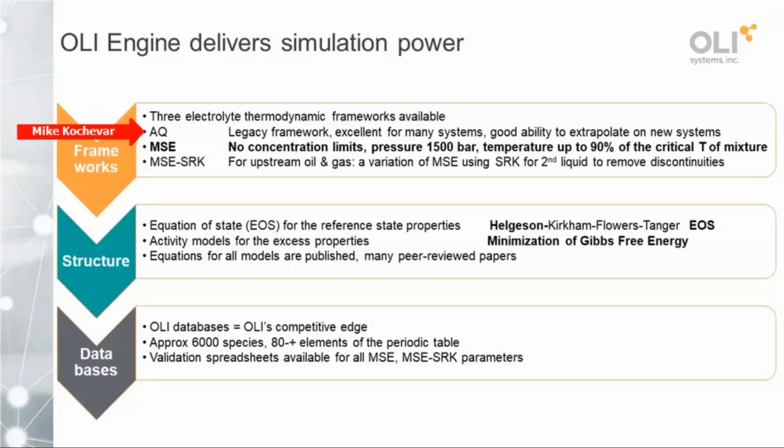So more recently, we've developed the MSE model, or mixed solvent electrolyte. This does not have that assumption of water, and so there's no concentration limit. We can go all the way up to 100% solute. Don't need water in the system at all to be accurate. You see still a very large pressure and temperature range that we can cover.